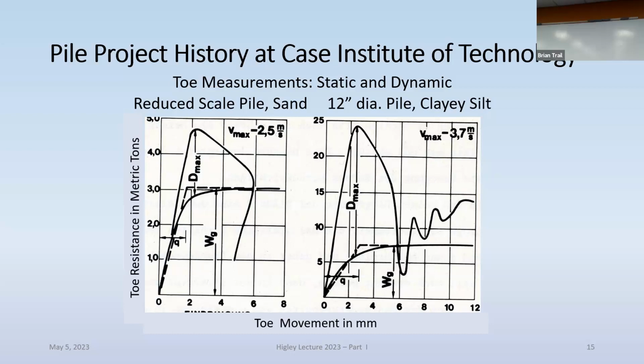The left-hand picture then took the toe instrumentation, acceleration and force, and integrated the acceleration to velocity. And so you see here the displacement when we integrate the velocity. And the maximum displacement here, of course, would be the time when the velocity is 0.